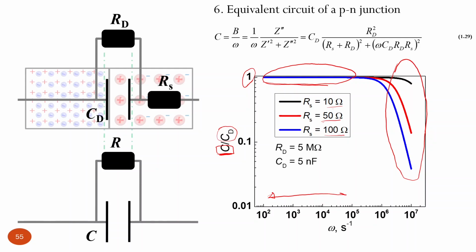So because injection and extraction happen even in an ideal device, and reality is not ideal, we also need to take into account defects and impurities, which can be charged and discharged in the process of applying AC voltage to the system. And eventually we have an issue with parasitic capacitance, which we measure.